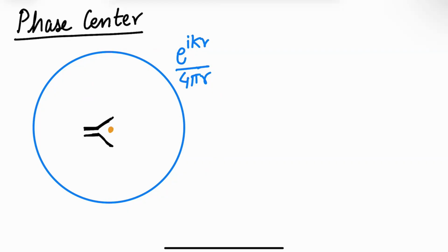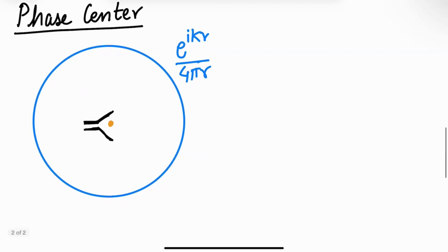Okay, so we often need to find this phase center because then we can use approximations like geometrical optics to design these reflectors, right? Because we saw that when you're at very high frequencies, that's the reason it's called optics, geometrical optics, because when you have very high frequencies, then you can approximate essentially rays going out.